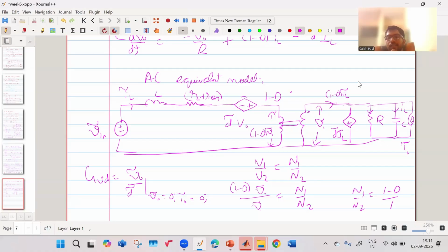Yes. So actually, inductor current is a state, right? Whereas your I output, your V in, those are like your disturbance or your actual system input, right? So that can be fixed. But your inductor current is an internal state. So it is affected by the dynamics of your system, right? So you cannot set your inductor current perturbation to 0. Similarly, you cannot just set your output voltage perturbation to 0, because it will be affected by any of the perturbations. Okay.